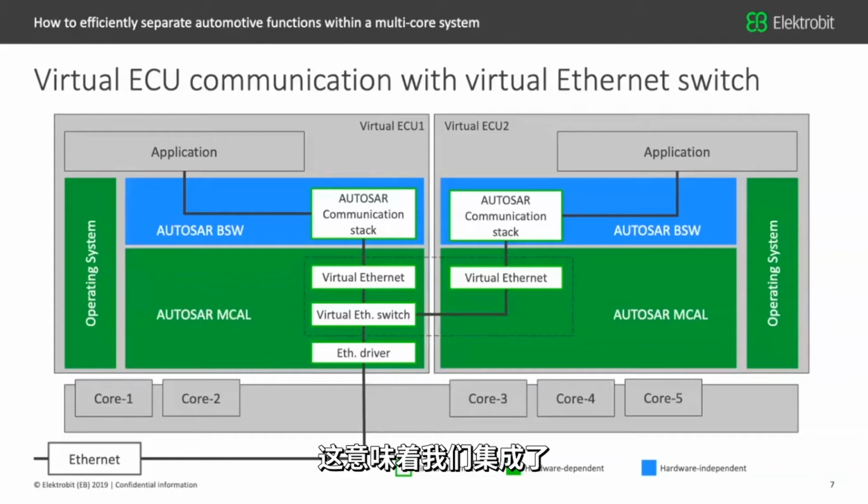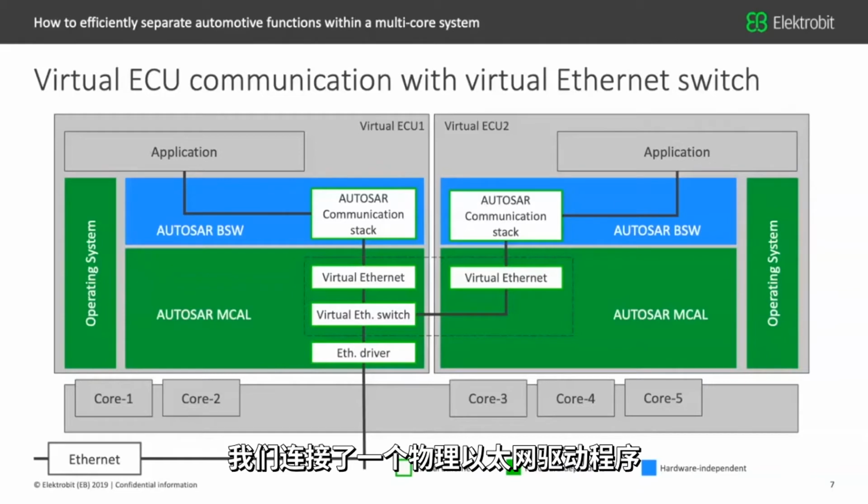That means we have a virtual Ethernet driver integrated, some sort of special MCAL, in each virtual ECU. And this virtual Ethernet driver is connected to the virtual Ethernet switch, which runs on the host system. Then underneath the virtual switch, we have a physical Ethernet driver connected, which then is connected to the outside world.